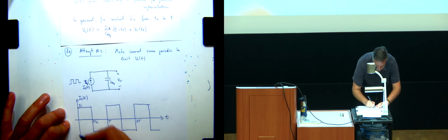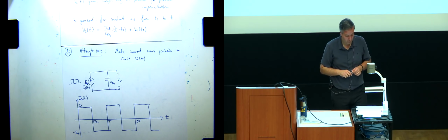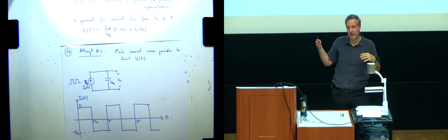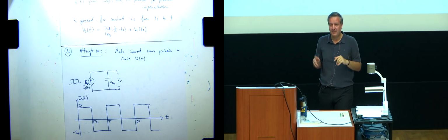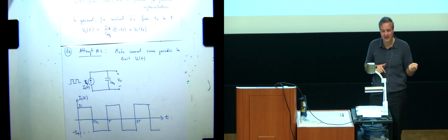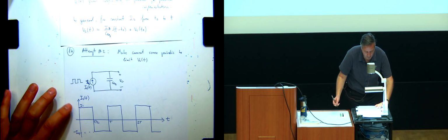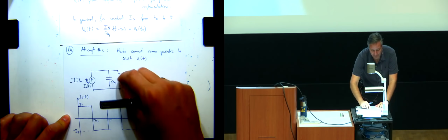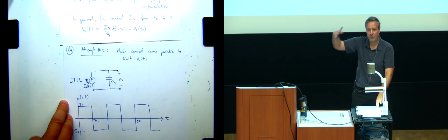And so this current is minus I1. So just imagine I have a source like this. You'll see in the lab we can actually, and later we'll actually make this source out of voltage sources and some op amps and stuff like that. But for now, let's just assume I have it. If I had a source like this, life is great, because during this period of time, I'm charging up the Vc, so the voltage is going up, and then during this period of time, the voltage is going down.